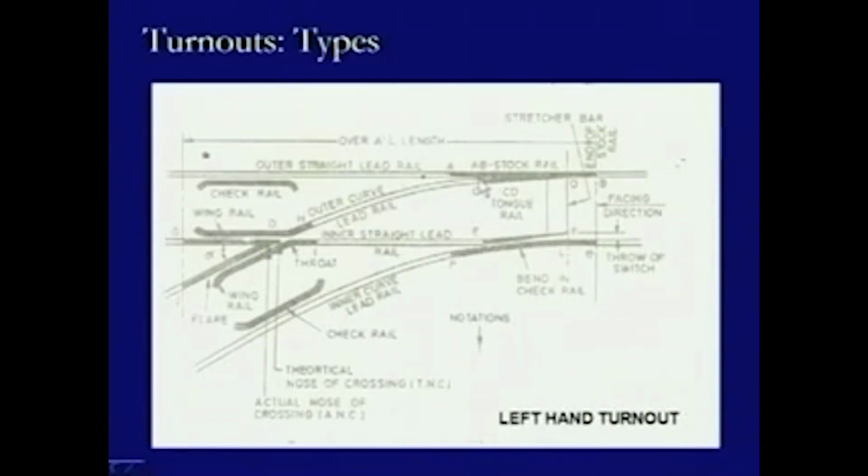So, there is one rail section which is being formed straight like this, and this is another rail section which we can see is a straight rail section, and this is having a thickness equal to the same rail section as being shown here. The thickness here means the thickness of the rail head. It has the same thickness at this point, but as we go further it becomes tapered and has a much lesser thickness at the end point. So, this pair of rails is known as the tongue rail.